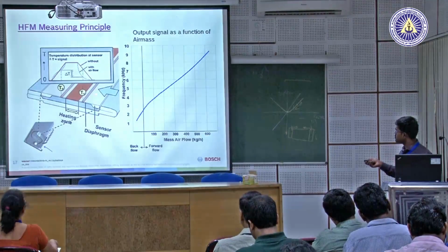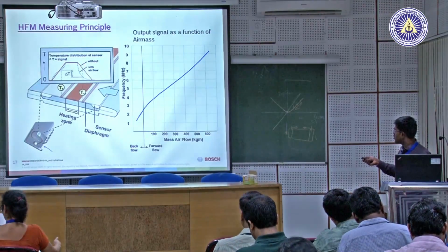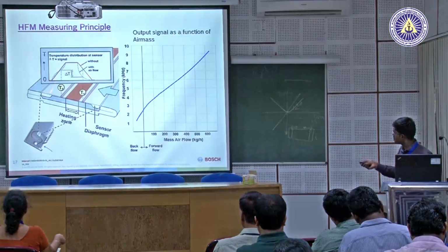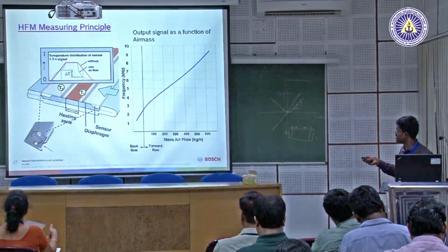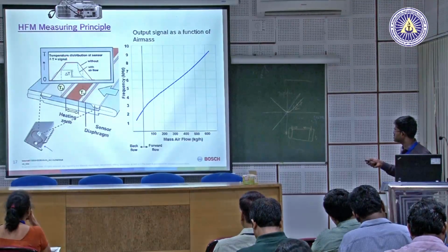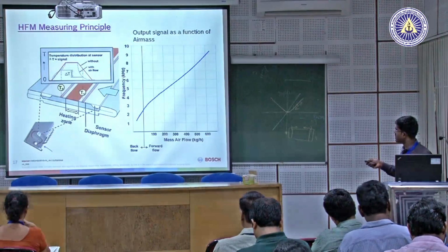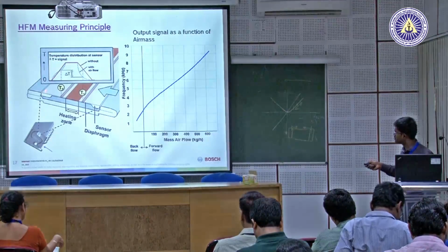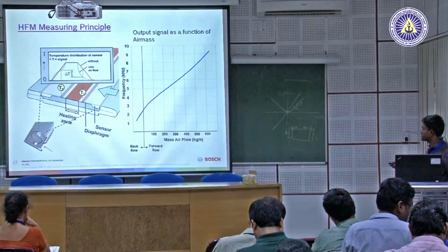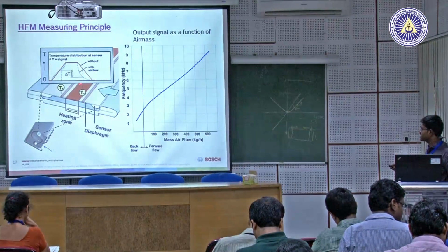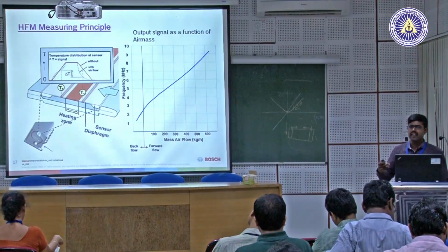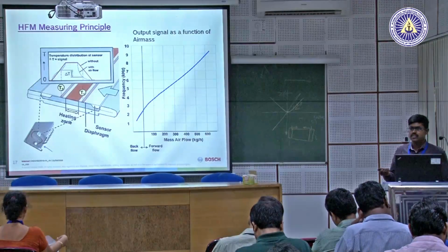So, the ideal condition is this red one. When you are heating at this zone, the temperature gradually increases and gradually decreases. When air passes, the heating phenomenon will be like this, there will be a bit of lag, and then again it attains the final temperature and comes down. So, what we do here is take 2 zones with 2 different temperatures, and you can see the delta T is calculated. If you have more air, it takes more time to heat it. So, that is the concept.